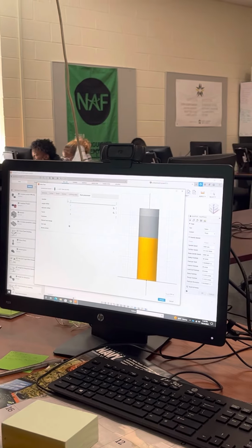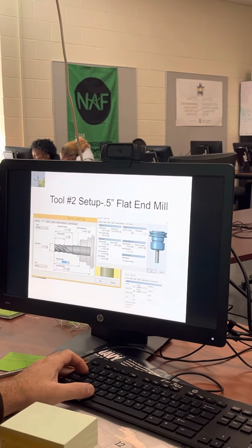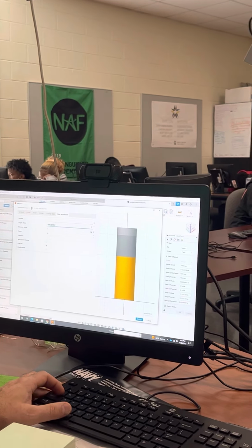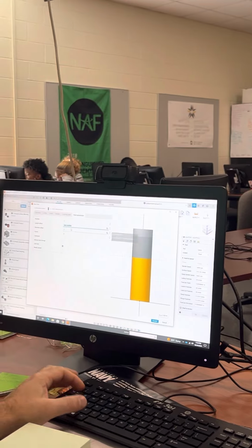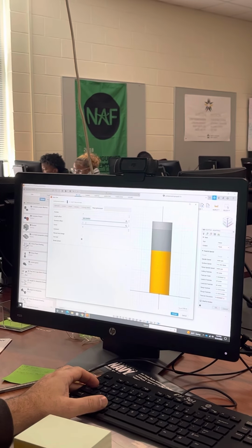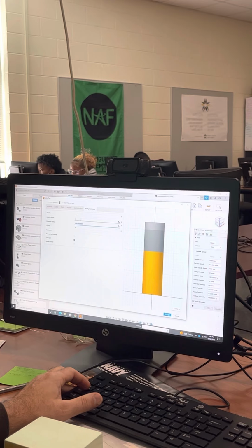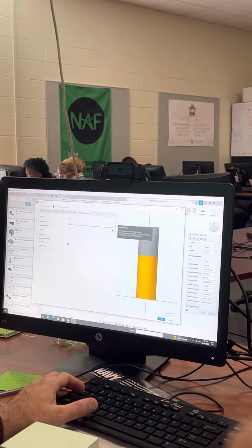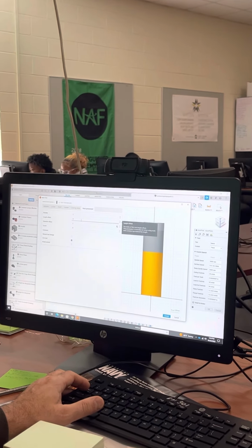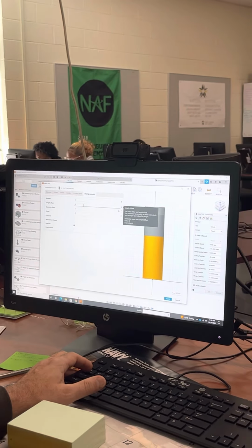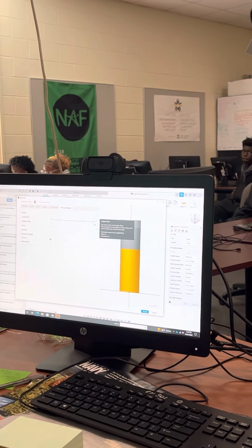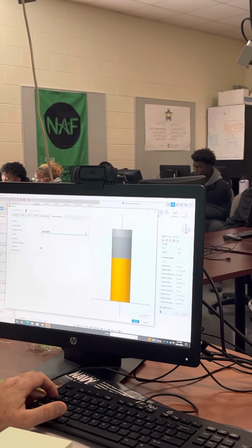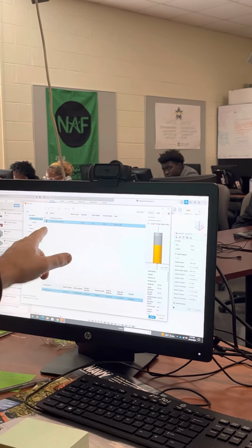Okay. We're gonna set tool number 2 up. So in our machine, it's positioned in the automatic tool changer as tool 2. So in the code, it'll be like referencing T2. There should be no length offset. I'm gonna set that to 0. Let's just read what that says. The index of the tool length offset for parameters normally set when you use tools with multiple tips. Okay. So we're gonna set it at 0 for now. And then that's it. So accept that. Our tool's set up. We're gonna select that tool.